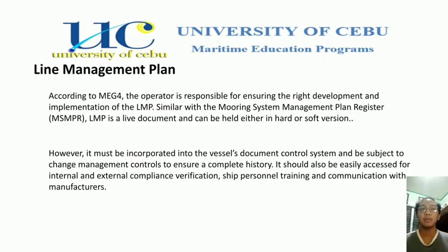Line Management Plan. According to MEG4, or Mooring Equipment Guidelines, the operator is responsible for ensuring the right development and implementation of the LMP, or Line Management Plan. Similar to the Mooring System Management Plan Register, or MSMPR, the LMP is a live document and can be held in either hard or soft version.